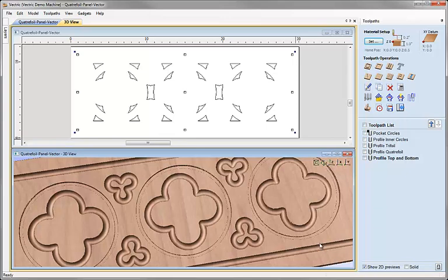As I move that over an area we've cut in the 3D view, it shows me the Z depth of that area. This is very useful if I wanted to eyeball, for instance, the area that we'd pocketed out and check its Z depth, and I can see there it's showing me a Z depth of -1/8 of an inch. So again, just a quick way of visually checking the depth of something. If you want to point the cursor at it, then on the bottom of the interface it'll show you the coordinate of the area you're pointing at.